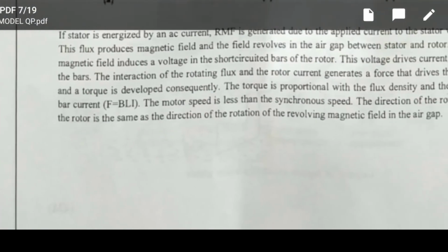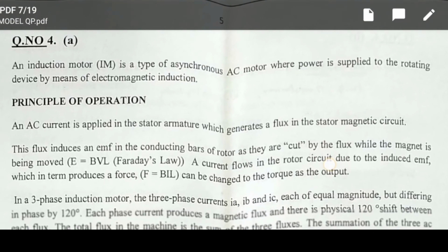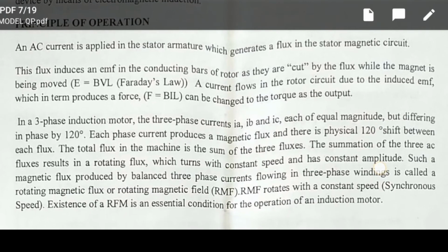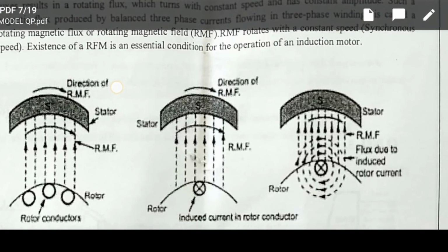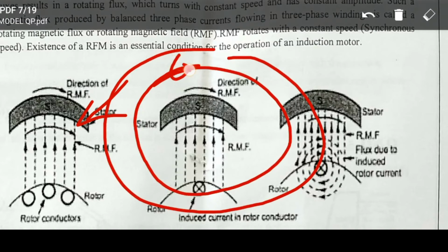Coming to the next question, what is the principle of operation of a 3-phase induction motor? Induction motor is not a synchronous motor. For the 3-phase supply we are giving, a rotating magnetic field will be created. That rotating magnetic field, RMF, rotates the rotor. Whenever we give the supply to the stator, the 3-phase induction motor having a stator with 3-phase distributed winding in the slots, a 3-phase rotating magnetic field will be created.